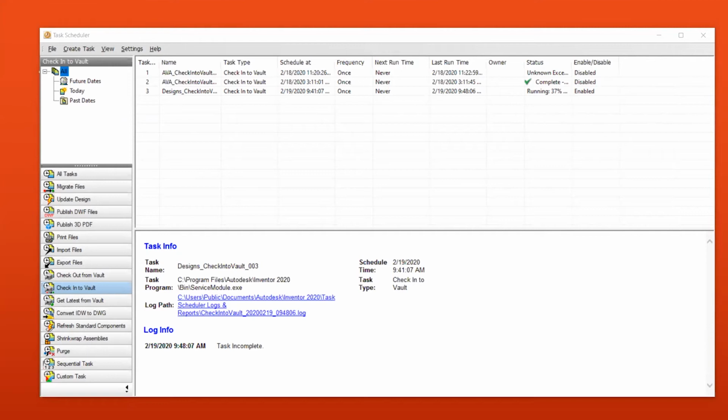Are content center files filed in the project folder versus the content center library? So it depends on how it is being structured there. Through the Autoloader, you saw that it picked up the content center files automatically and placed them there. If it's designed with a content center library part versus a library part, the difference there is you can have your own library inside of Vault of parts that it's picking from. It doesn't necessarily have to be a content center library. So depending on how it was built and designed, it'll go ahead and check it in that way.